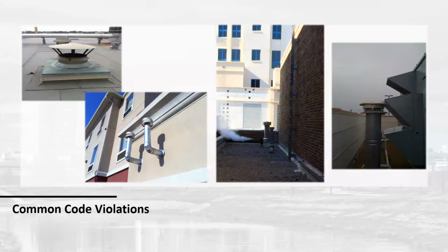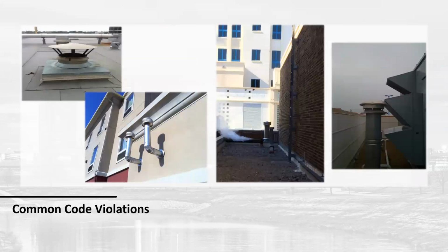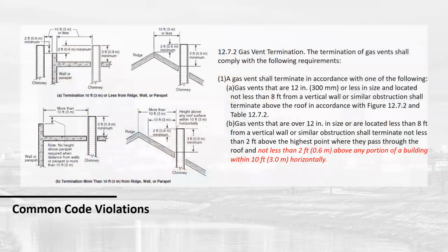So, Hey, Jason, real quick. Yep. Before you move on, I have Eric Polito asking where the 2/3 rule comes from, which particular code? Sure. I believe this is NFPA 54, Chapter 12. So it stems from Category 1 appliances, but it actually holds true for all. If you read later in the code, it does extend into that as well. Okay, thank you. No worries.